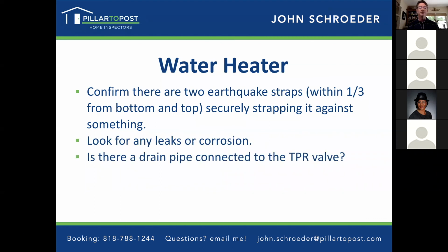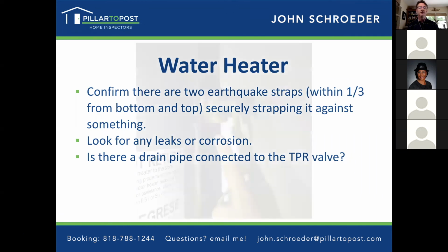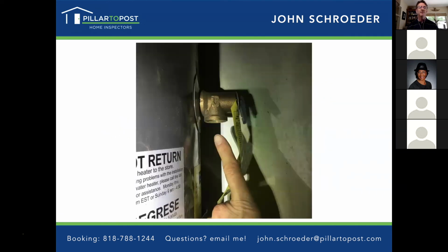Is there a drain pipe connected to the TPR valve? That's the temperature pressure relief valve. It looks like that, and that does not have a pipe attached to it. But if there's a failure in the system, you can have really high pressure, very, very hot water come spraying out of that, and it needs to be directed someplace where it won't cause damage.